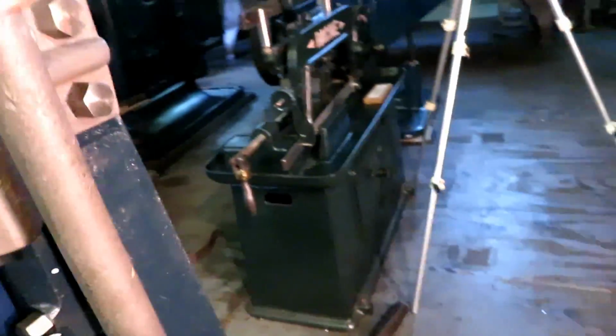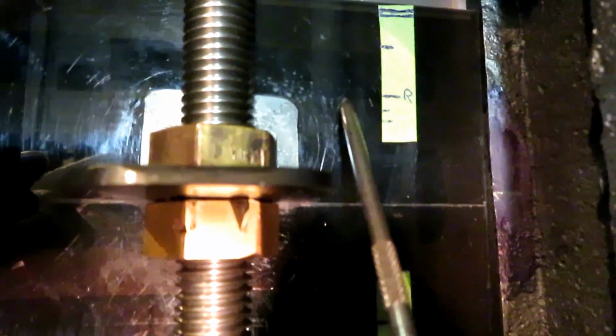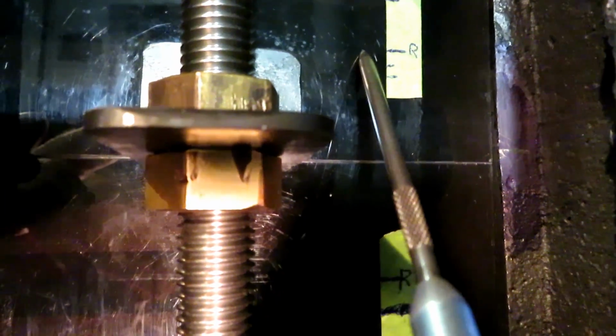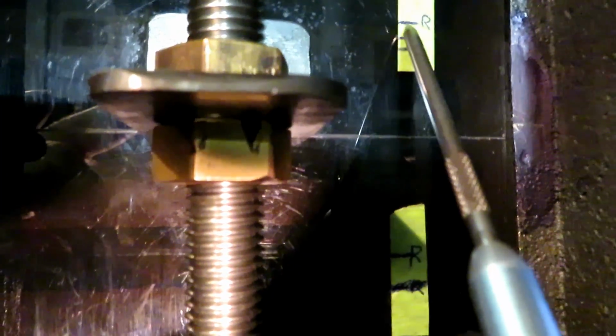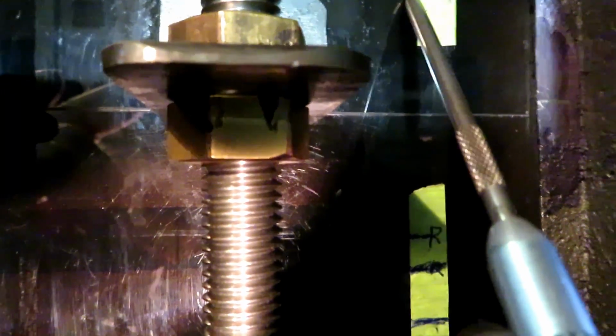At the release, I don't know if you can see it, but the edge of the port behind the plexiglass is right there. So I'm going to make a little mark over here and label it R. That's the release, and that's going to be the top edge of the exhaust port on the back side of the slide valve.